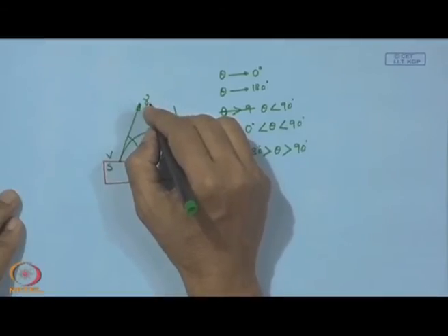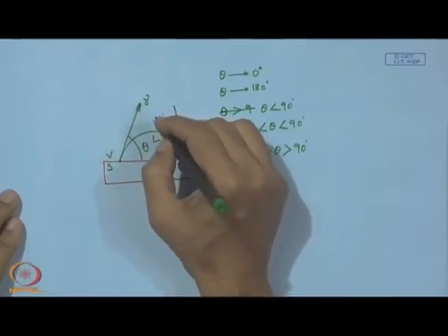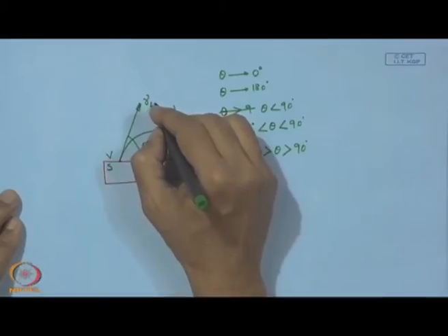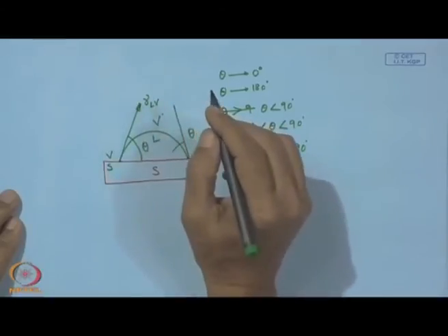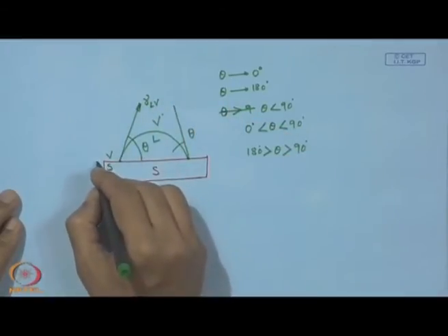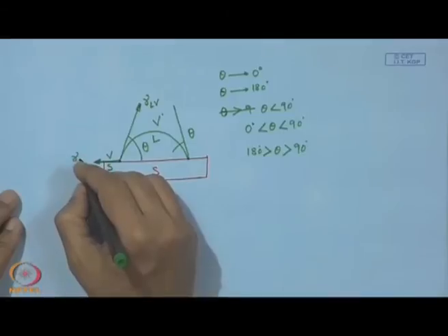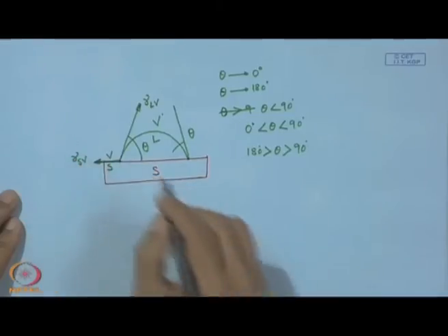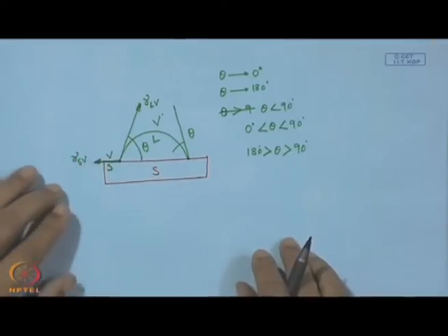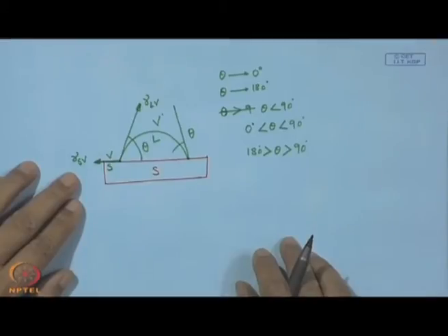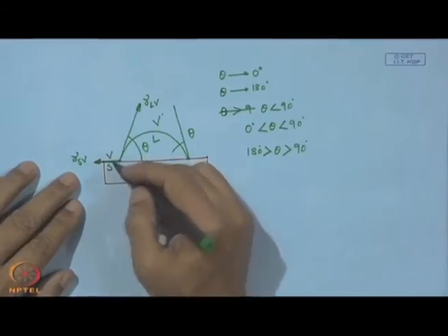Now, here along the line of tangent we have one force, that is actually the interfacial energy per unit area at this vapor liquid interface, and that we can put as gamma LV. Similarly, in this direction along this surface we can also have gamma SV, that is the interfacial surface energy per unit area at this vapor solid interface.